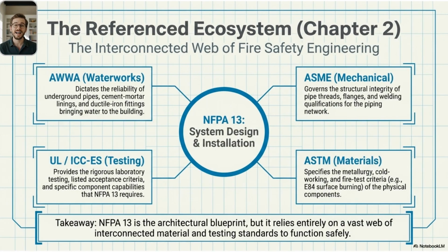NFPA 13 relies on an ecosystem of reference standards like AWWA for waterworks, ASME for mechanical integrity, UL and ICC-ES for testing, and ASTM for materials. NFPA 13 is the blueprint, but its function depends on this interconnected web.